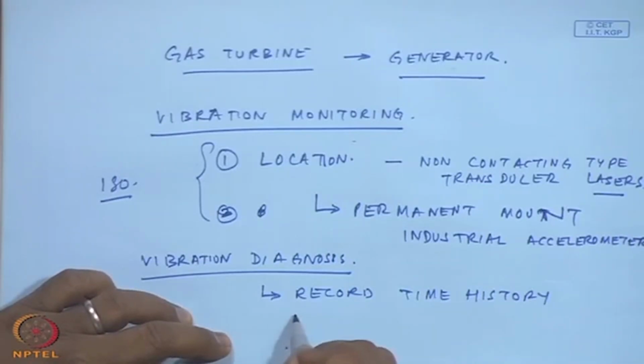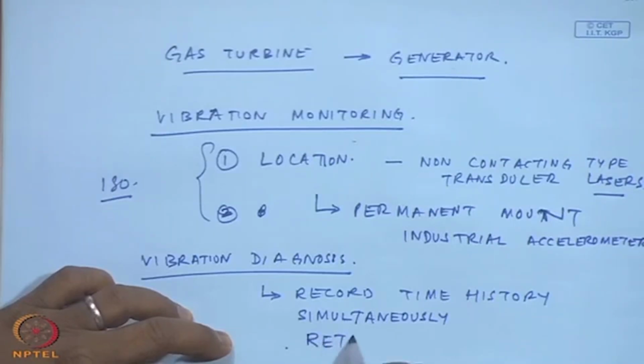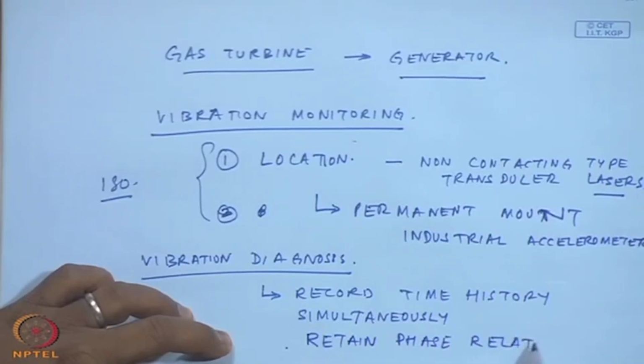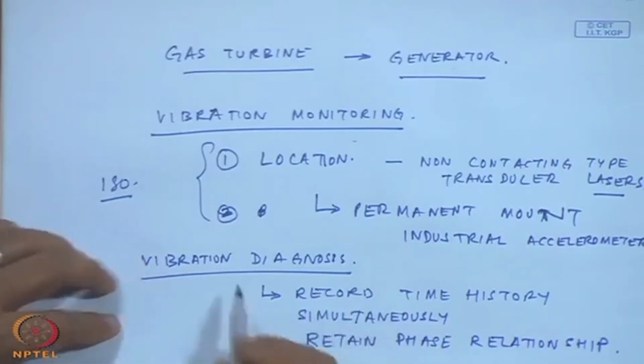I have to record simultaneously. Why do I record simultaneously? To retain the phase relationship. This is very important when we are doing the diagnosis.